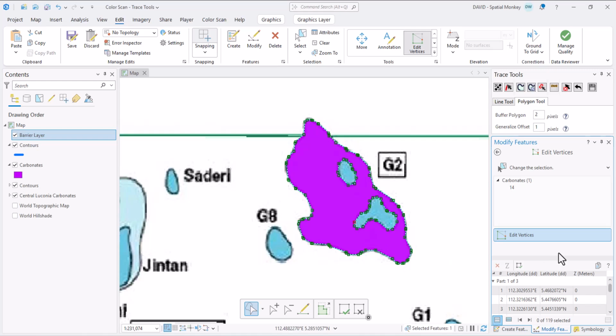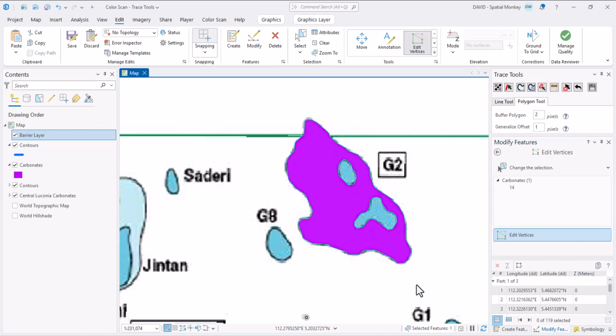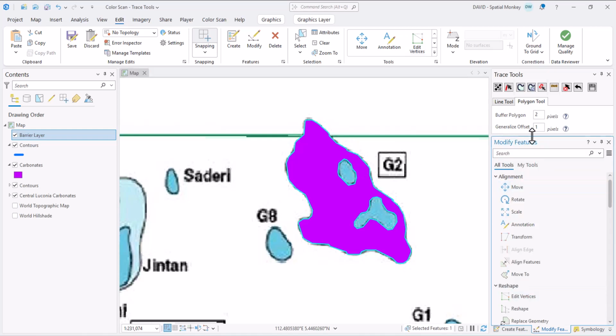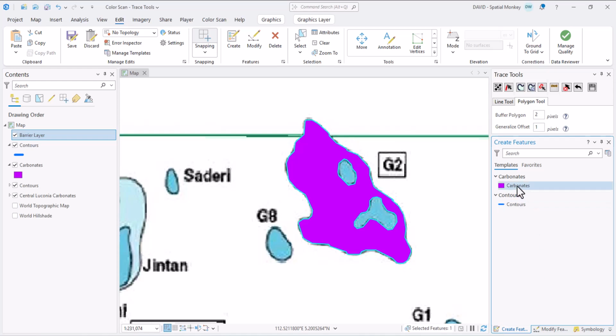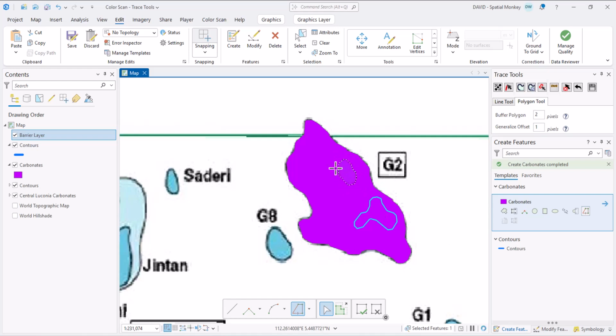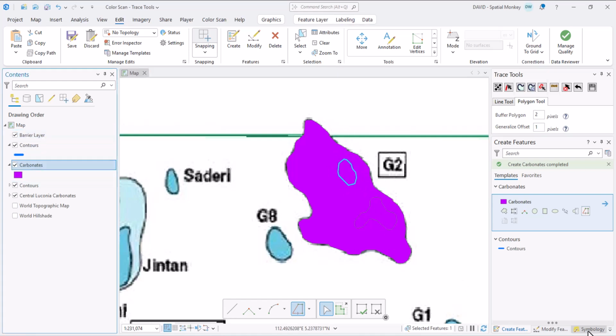Bearing that in mind, to create the internal polygons, we could auto-trace further polygons there, but we would not get a perfect fit without any gaps or overlaps. So instead, it would be better to use the Pro Trace Create features. And we can fill those holes in to get a perfect fit between the polygons. Let's just modify the symbology to see the border better.